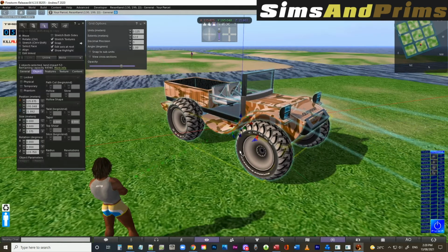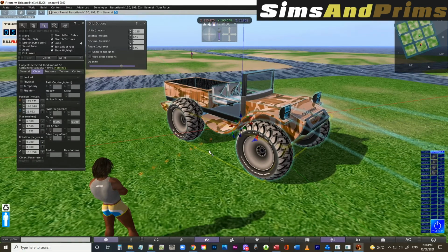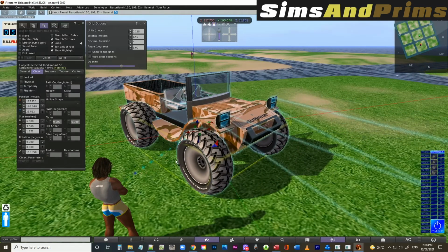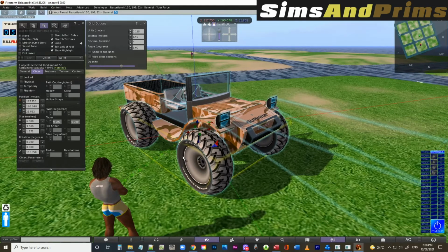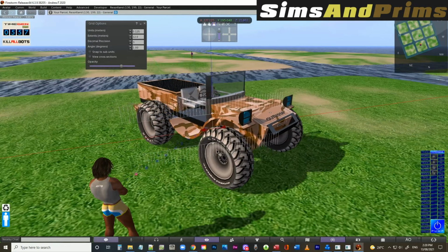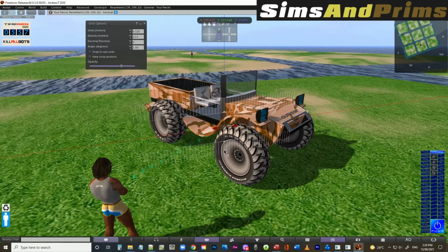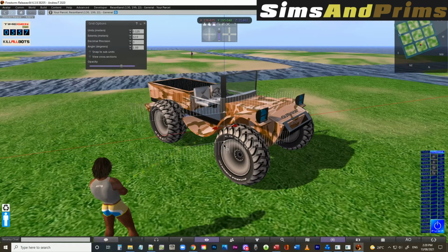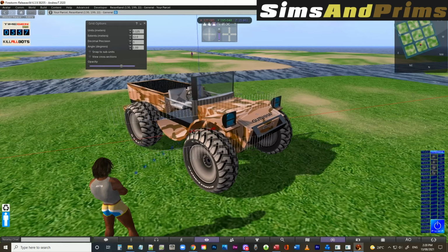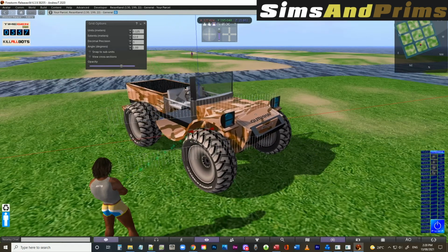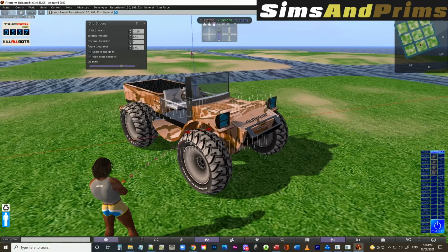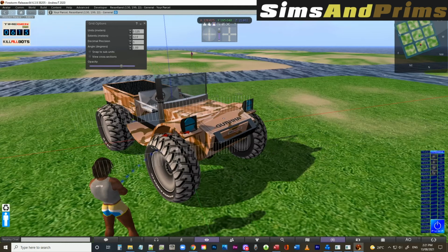You could just as easily make it 0.1, which probably makes a bit more sense really, but I'm just used to using half meters and quarter meters quite a lot, so I find it very convenient to use that 0.125. Anyway, if you're out here in these grid lines, you'll see that it snaps. But if you move your cursor out of those grid lines, see how it moves freely? It's not snapping. So if you don't want it to snap to grid, you can move it like that. If you want it to snap to grid, go down to the grid lines.